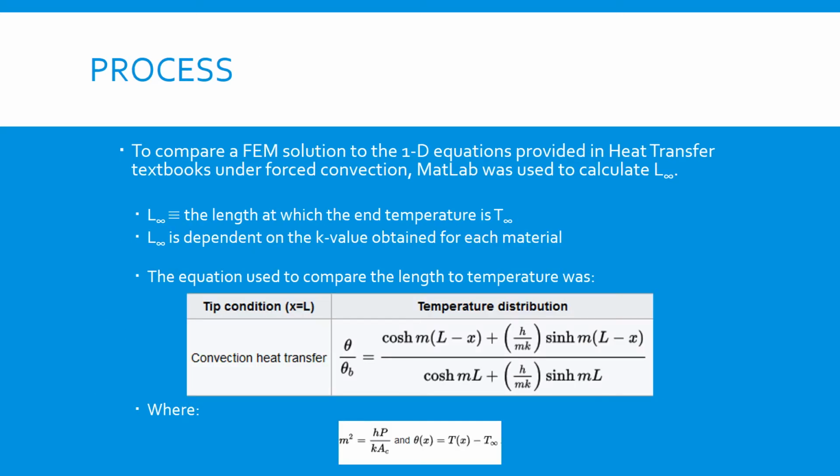The one-dimensional heat transfer equation shown was run in MATLAB for a fin of 2 cm diameter to determine when it could be considered infinitely long. The test was run separately for copper, aluminum, and stainless steel because they have different conduction coefficients.